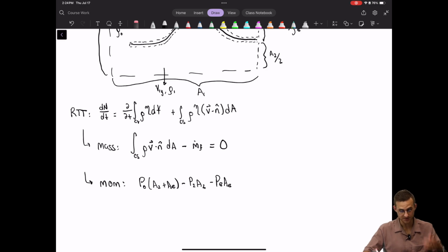And then there's also the friction forces, right? So we can integrate over AW, which is us integrating over the wetted surface of the propulsion system. And there you have the overall stress tensor, which is P, the pressure, times the identity minus tau, which is the full stress tensor, dotted with n hat dA.